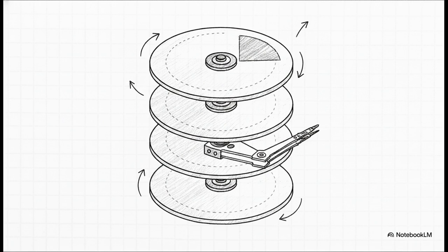For secondary storage, things like magnetic hard disks, the physical organization is just a marvel of engineering. The disks contain platters with recording surfaces on both sides. To actually locate your data, the disk physically rotates. So your total access time is a combination of the time it takes the read arm to seek the track, the rotational latency waiting for the data to spin around, and the actual transfer time itself.